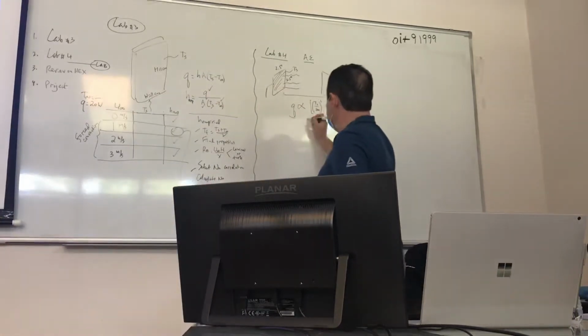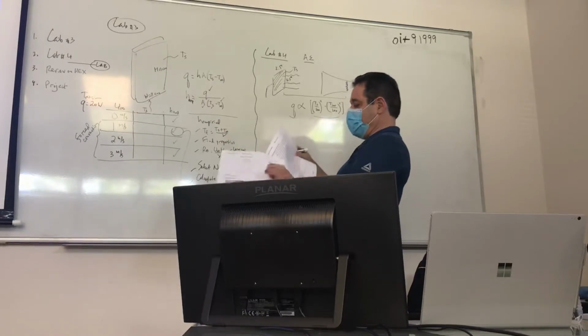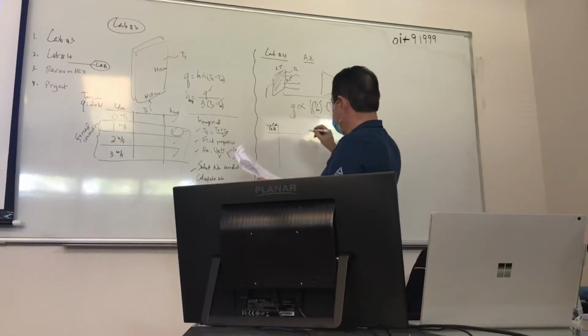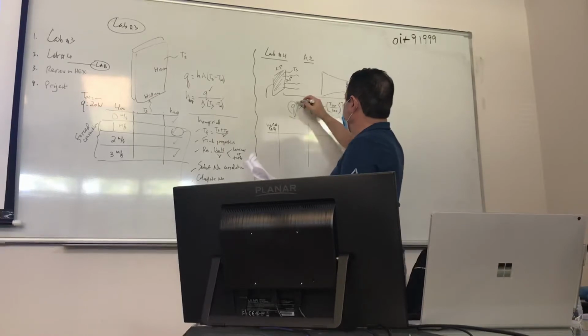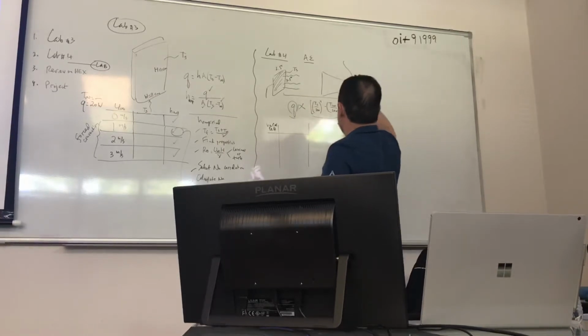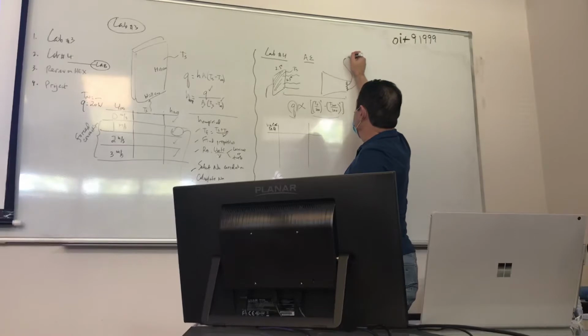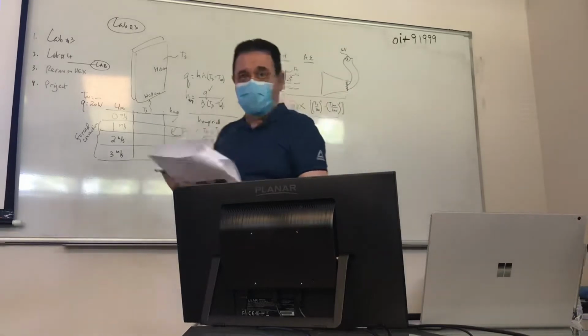It tells me that Q should be proportional to this. Now, how am I going to establish the proportion? First of all, there's a table in the back that gives you the variac setting. Variac setting meaning just how much voltage you're gonna put into the system, right? And then remember, this Q is read by what? Remember, we're connecting this to a voltmeter, right? And this voltmeter is gonna tell us the number of millivolts, right? The more heat, the more millivolts you're gonna get, right?